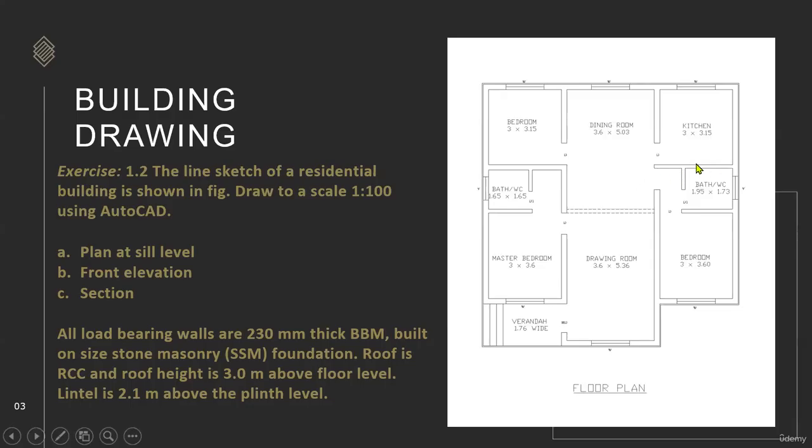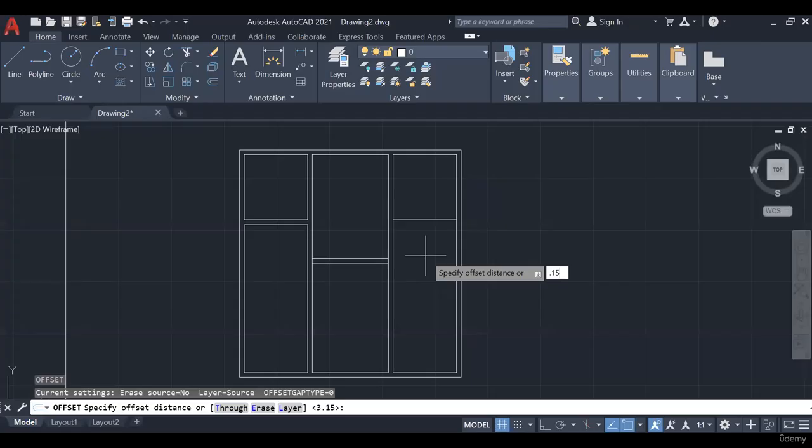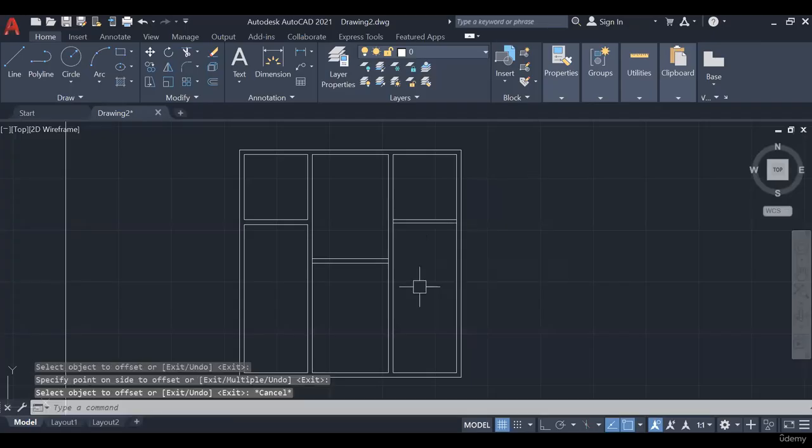This is a partition wall. Here it is not mentioned as a partition wall, but here it is mentioned as a partition wall. So that depends on that. But in this plan it is mentioned as a partition wall, then we need to take the partition wall only. We are considering in this particular plan that it is 150 mm. Just go here, offset I have taken 0.15. Press enter. Okay, so these three rooms are ready.